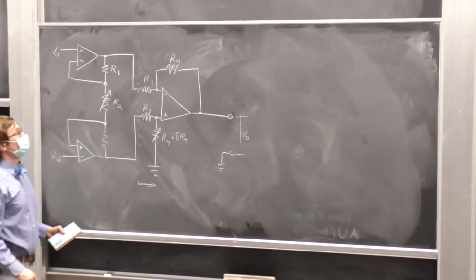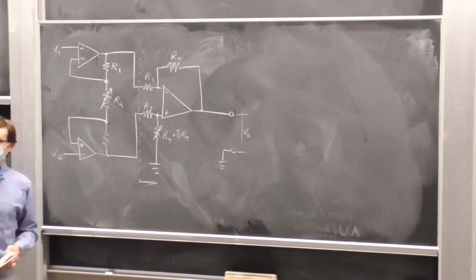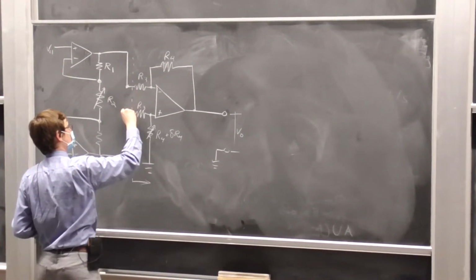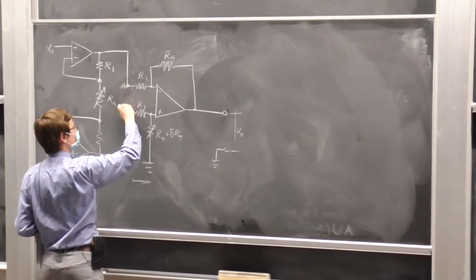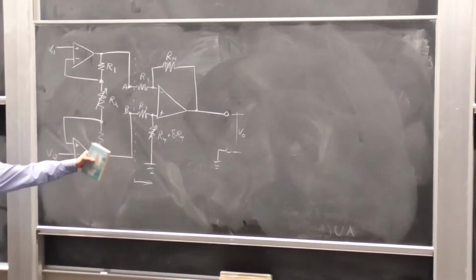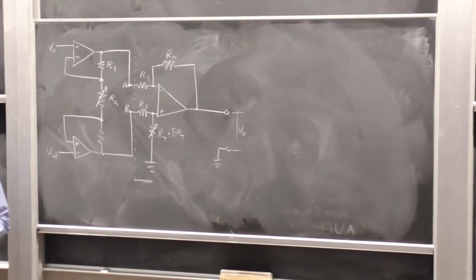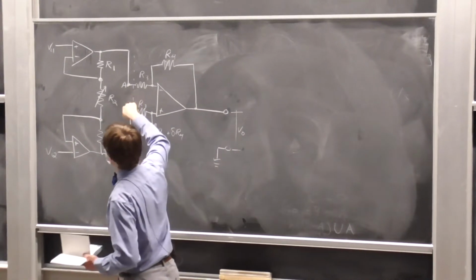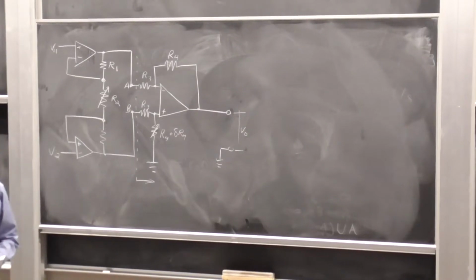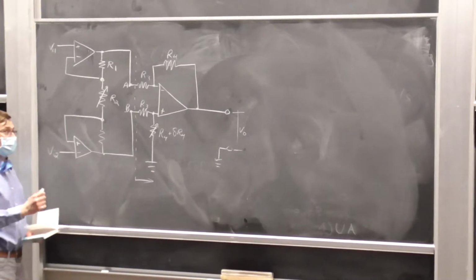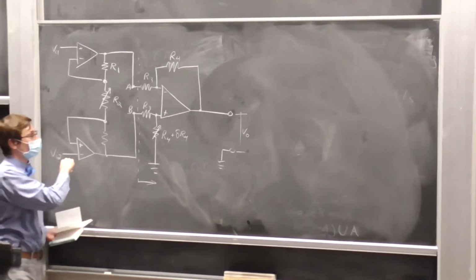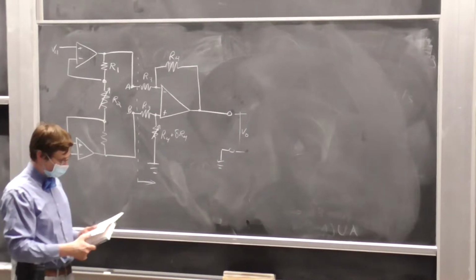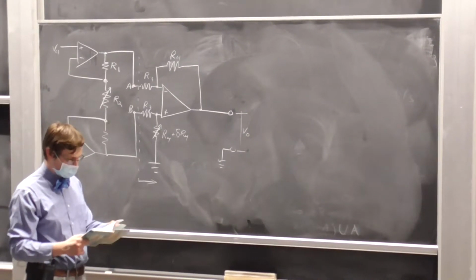So, if we consider two of the voltages that we're interested in as being the voltage here and the voltage there, let's call these points A and B, we can use the equation which we have already derived for differential amplifiers to relate VO to voltages A and B. Once we have done that, if we can find some way of relating VI1 and VI2 to voltages A and B, then Bob's your uncle. All right? Which is a very British way of saying we have completed the problem successfully.